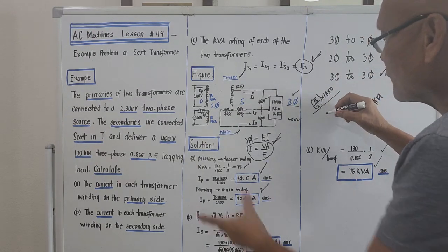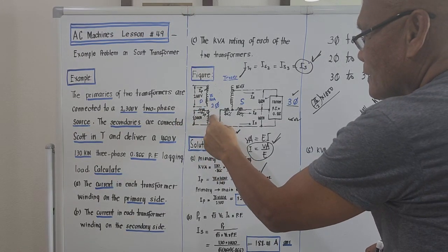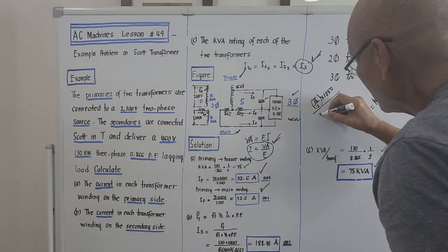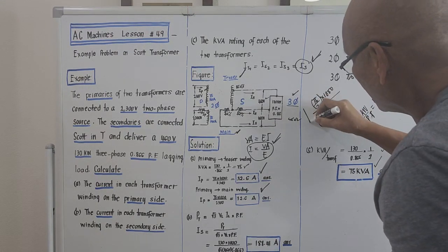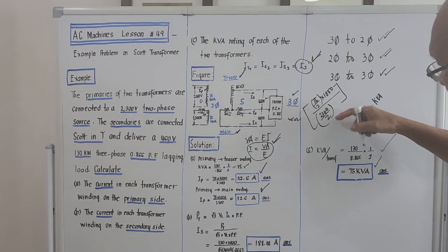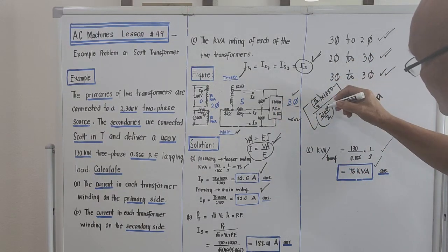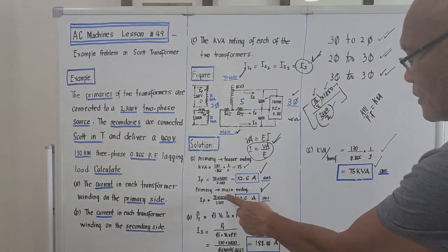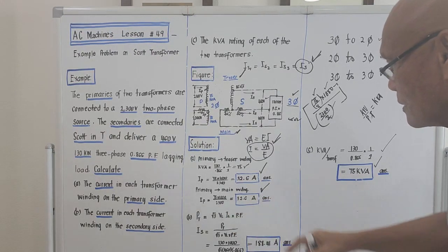as another solution. And the voltage should be, since this is 2300 and they are in phase here, the voltage per 50% is actually 1 half of 2300. So this should be 2300 all over 2. Okay. There is an over 2 over here. There is an over 2 over here. Actually, these two here cancel with this. Anyway, the operation is multiplication. So it will still be the same 75 times 1000 over 2300. 75 times 1000 over 2300. So it will still be 32.6 amperes.